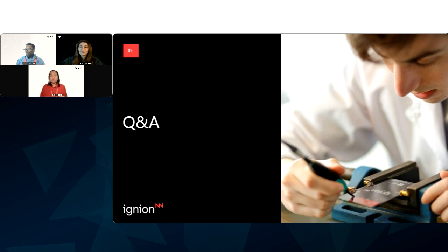The first one, we received a question from Luis. When using a 7-element matching network, can you share any general rules of thumb for adjusting component values? For example, to improve return loss in the low band, is it helpful to increase the ZX and decrease ZY? Or is it good to shift a good RL peak toward a higher frequency band? What adjustments typically help? Maybe Sifiso, you can start with this one.